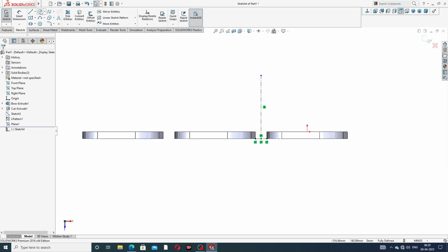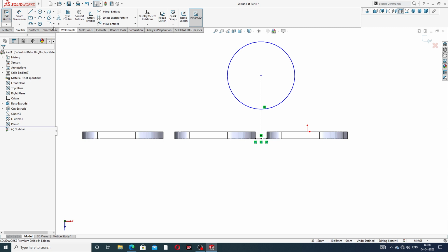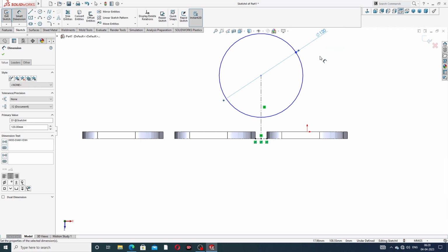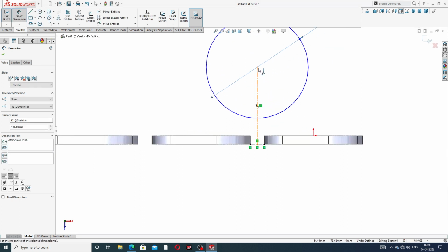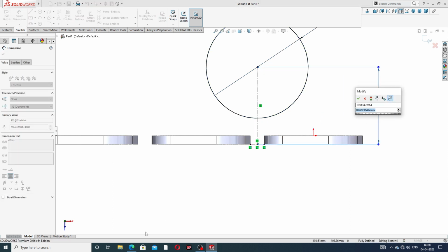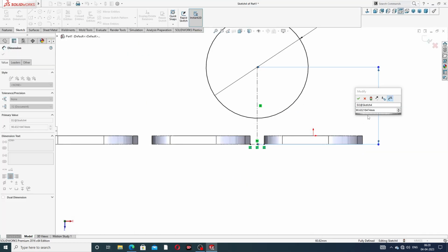Okay, and drawing a circle. The big circle is drawn here, and this diameter is 120 millimeter. Okay, and this point to this distance is 140 millimeter, and correct. Okay, 140 millimeter, and this small circle has a diameter of 12, and the distance from the center point to this is 50 millimeter. Okay, and this distance is 140 millimeter, which is correct.